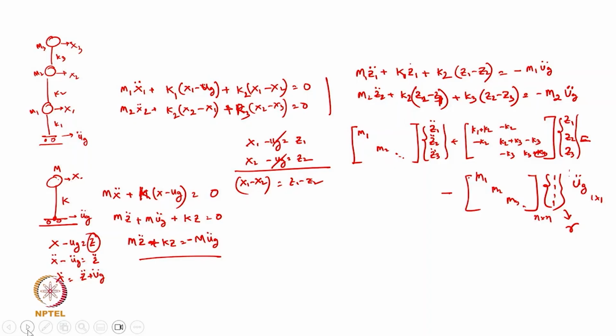Okay, so in some of the cases you may just see m, whatever is coming here, that is the mass participation. So if I just say m_e, then m_e divided by total mass should have some value. Like this, that is for first mode, second mode, third mode you are doing.